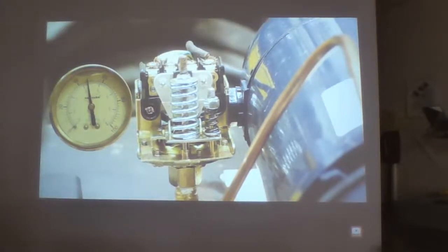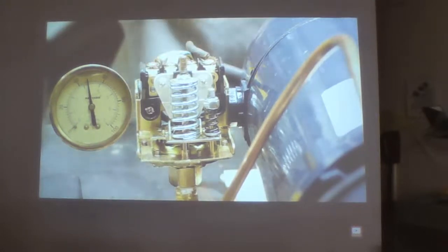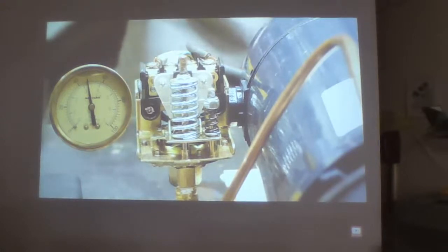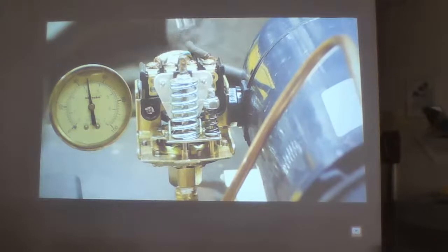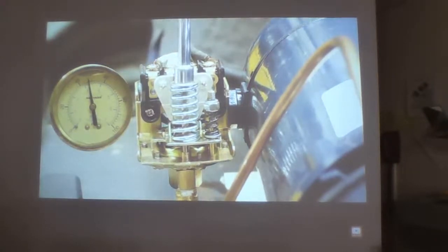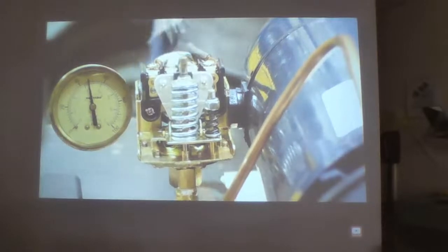And what we want to do for this example is we want to run at 60 PSI, so we want to increase this factory set switch to a 60-40 split. So when I say 2 to 3 PSI per turn, that's going to basically be 3 to 4 turns for us to increase it. So we have the breaker shut off. So now we'll get on here and do 3 turns.